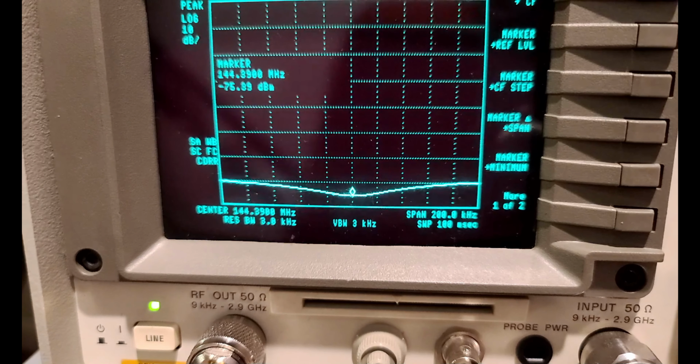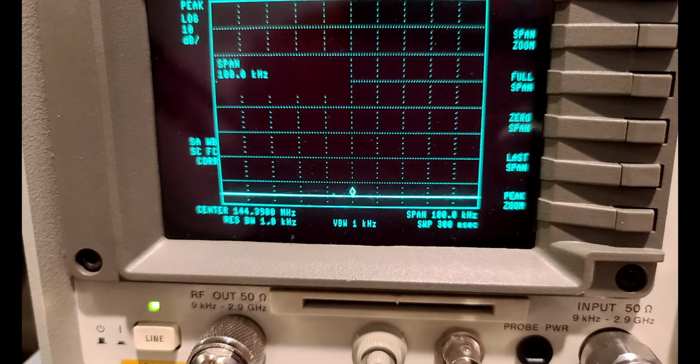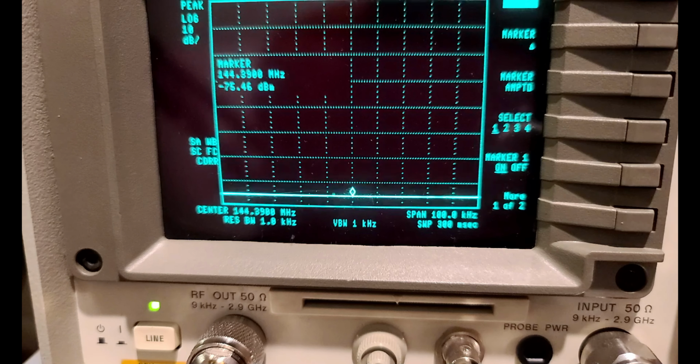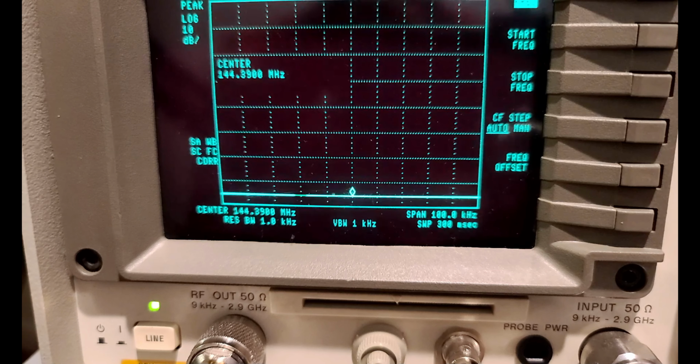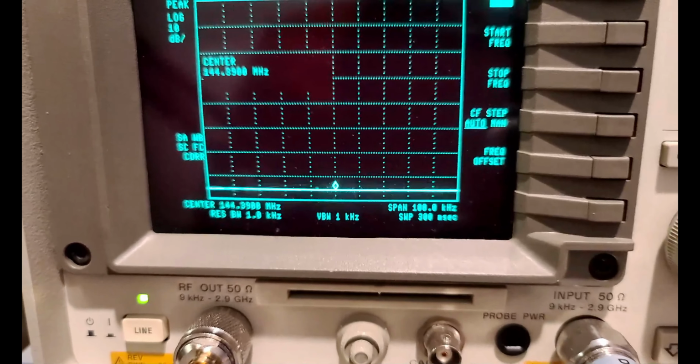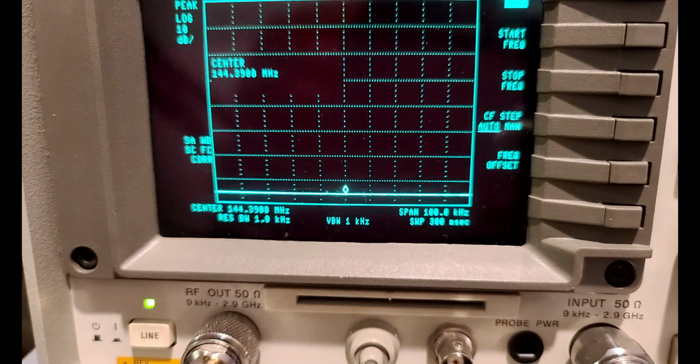We can further zoom in, let's say 50, or actually hang on, 100, no, hang on, span 100 kilohertz. And let's go to marker and the frequency. I think we are nailed in, so pretty good. So in any case, I wanted to show you the return loss method if you are venturing into tuning a cavity filter through the use of a directional coupler like I have here, through a spectrum analyzer with a tracking generator.